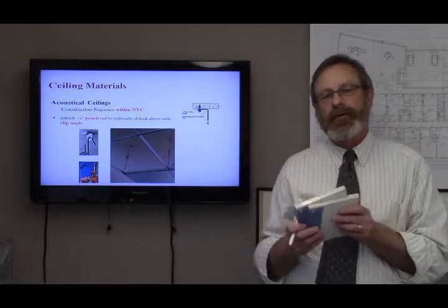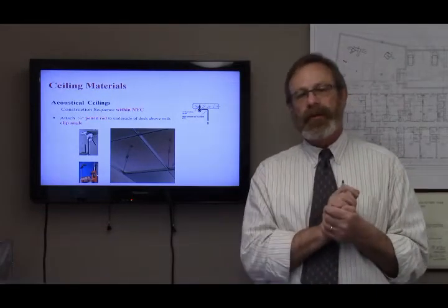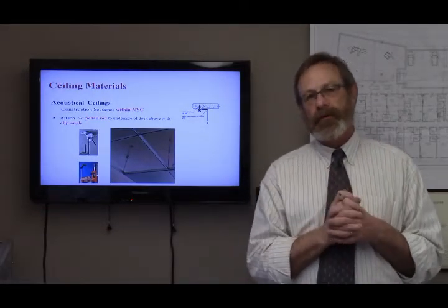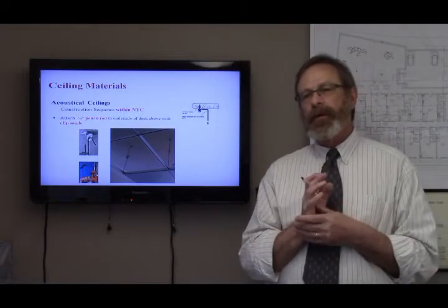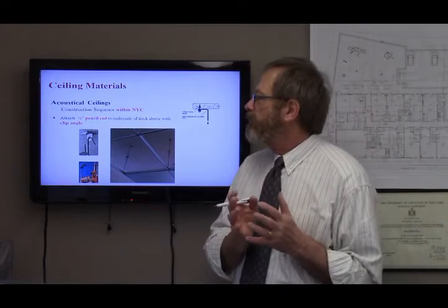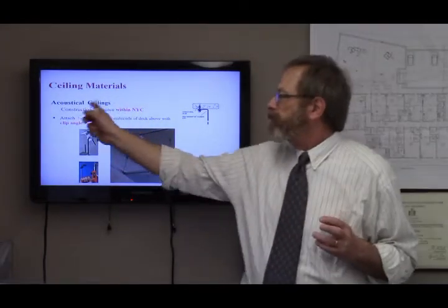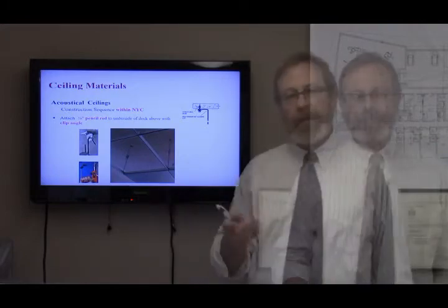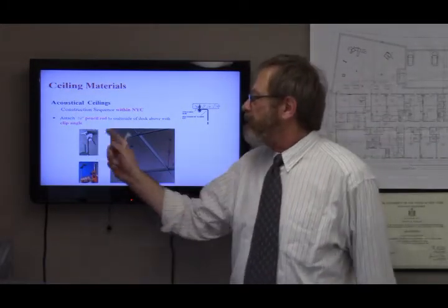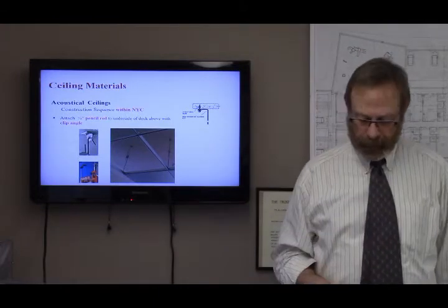We spoke about those types of ceilings, and the regulations for putting those ceilings is much more strict in New York City than it is throughout much of the rest of the country. So we're going to talk about first how the sequence of construction within New York City for acoustical ceiling tiles works. It begins, of course, with the clip angle securely fastened to the structure up above.